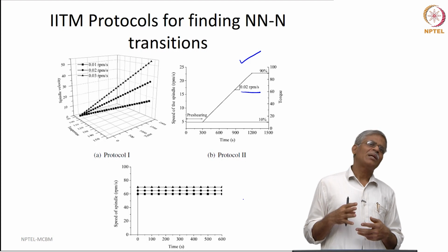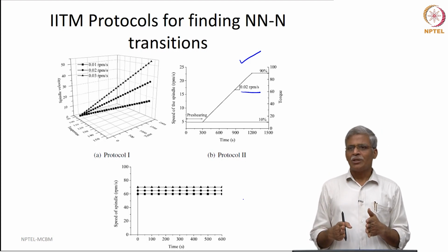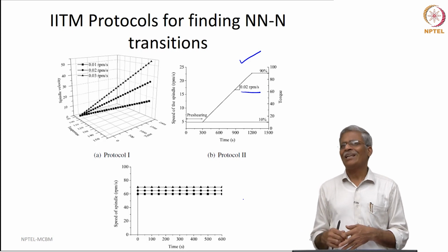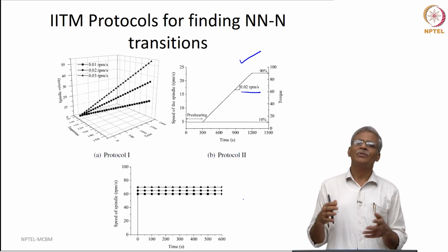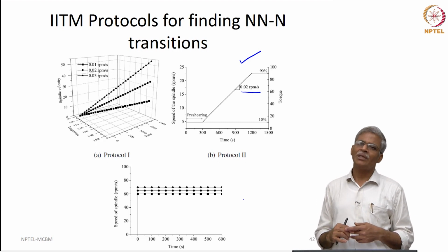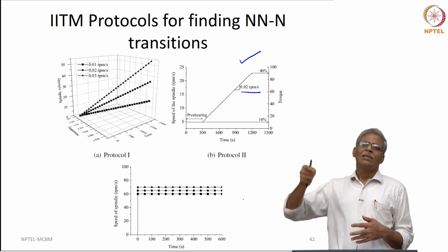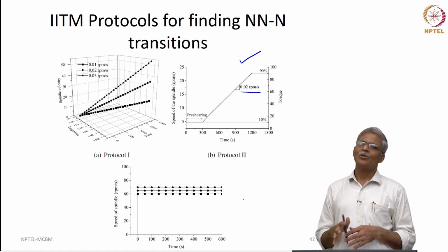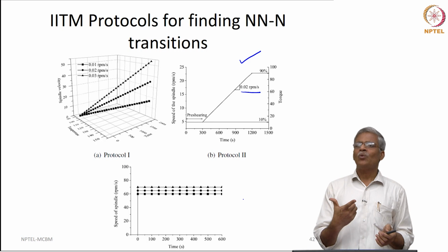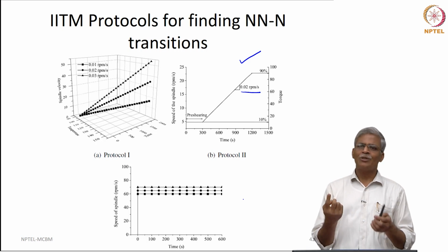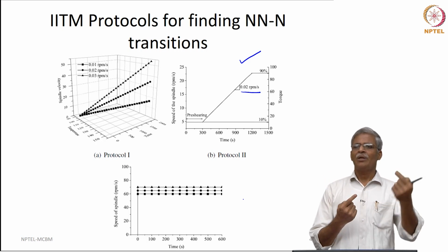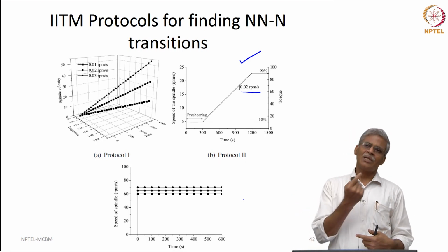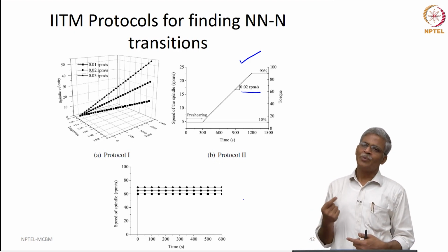We know very well that during the rolling operation, when it is subjected to very high shear rate, the binder can actually shear thin because of the non-Newtonian behavior of the material. But then the temperature also reduces and the viscosity can increase. So, we have to find a way of understanding these two contradictory things that are happening: viscosity reducing because of the shear thinning behavior, and viscosity increasing because of the temperature reduction.